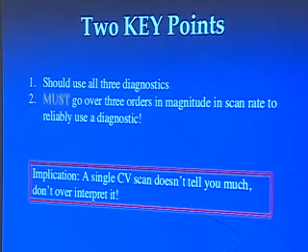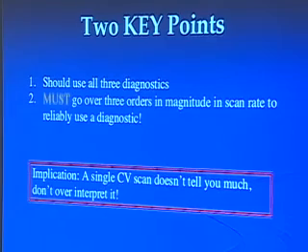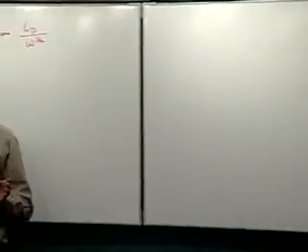However, they're not going to come in with 3 orders of magnitude, because if you think about what happens there, most machines easily go up to about 500 millivolts a second, or maybe 1 volt a second. And after that, you start to have to work a little harder because you need fast current to voltage converters and good data collection and things like that, or an oscilloscope, heaven forbid. And so people usually don't want to go faster than 1 volt per second.